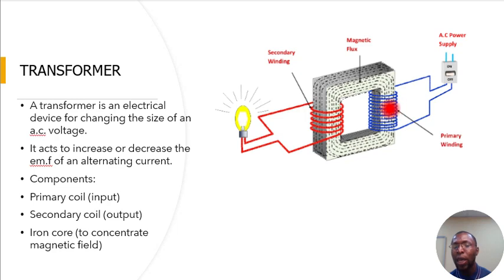This shows that this is a step-up transformer, because the primary circuit here. So in this case, this blue side is the primary. I label here as primary. Okay, the primary voltage here has more turns than the secondary voltage. Now this shows that this is a step-down transformer, not step-up, because the primary voltage has more turns than the secondary voltage. So the primary is the one that gets the external supply, and by the time it's sent into the secondary, because the secondary turns are fewer, it sends a lesser voltage.